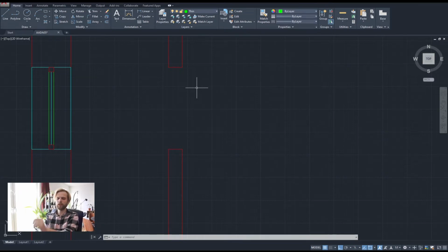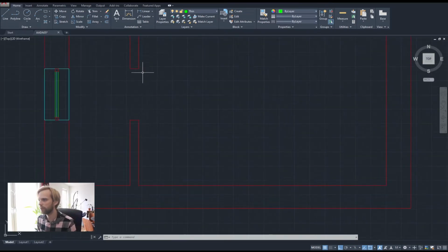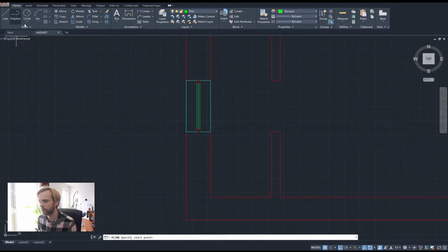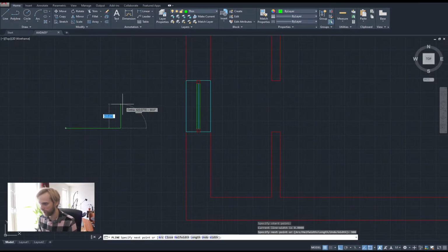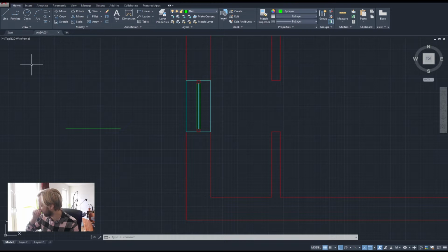So the door is basically drawn, I can show you somewhere here. The door is basically just drawn as always being opened, unless it's a reconstruction project and you already have existing doors in the previous project which you reconstruct, then those doors are usually shown half opened at a 45-degree angle.